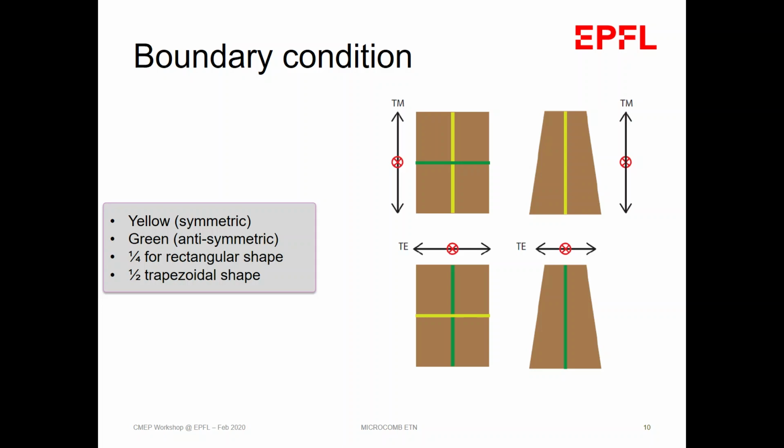Okay, a simple question: where is your 14% of energy? Where is the gap? Okay, first of all, your refractive index is different. You're coupling from air to nitride, so some light will get back reflected. You're losing some there, and also your mode is not perfectly Gaussian, but more trapezoidal, so the overlap is also not very good.